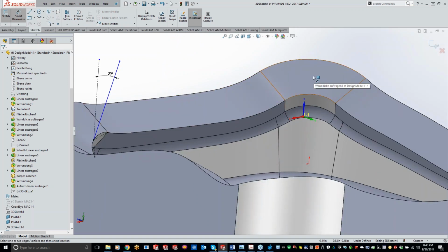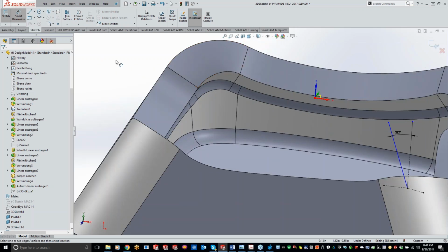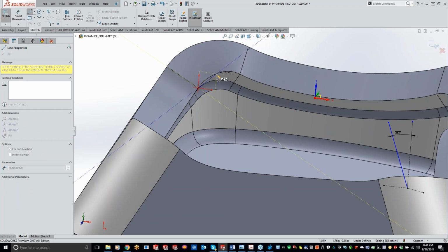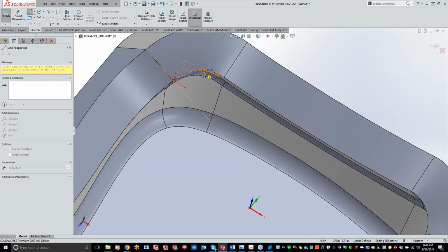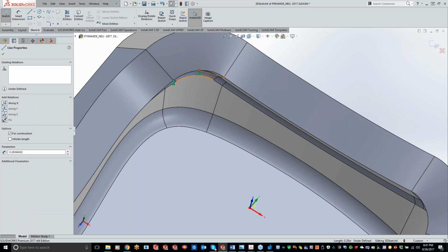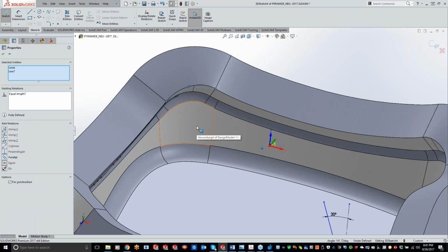One other thing I would say, and I should have mentioned this earlier, do the two equals over on the opposite corner to get that midpoint. Okay. And then we'll show them how to line that up so it's truly aligned towards the center of that arc, or the center of that curve, I should say. The reason that line is still blue is because we haven't constrained it on the other angular function. So once he makes these two lines equal, then that midpoint would be right towards the center of that arc or that curve.